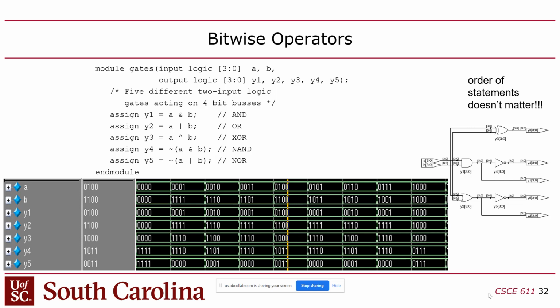So anyway, those are 4 bits, but of course you have to keep in mind too that if you're thinking in your head, I want these to be 4 bits, you have to internally subtract 1 to get 3, and then :0 because the 0 is inclusive. It's 3, 2, 1, 0. So every time you declare a signal with n bits, you've got to subtract 1 from n to put in the code, which is obnoxious, but that's what they require you to do. It would be much more efficient just to say 4, right? Because that's what I want, 4 bits.